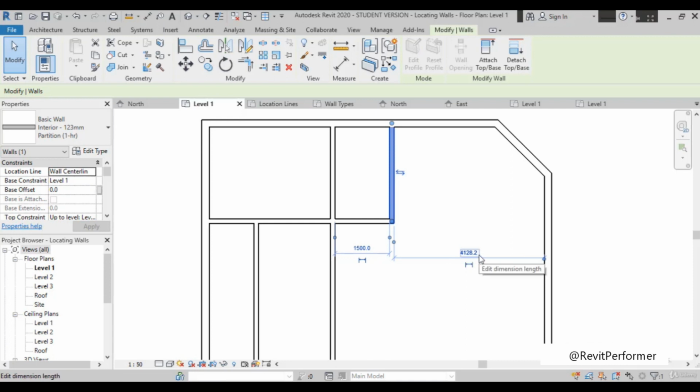That is because when you use these dimensions, they are temporary dimensions. When you move this wall, the wall that is selected is the one that moves. So be careful which one is selected. Suppose you want this 4000, so select this 4000 and take 4000.